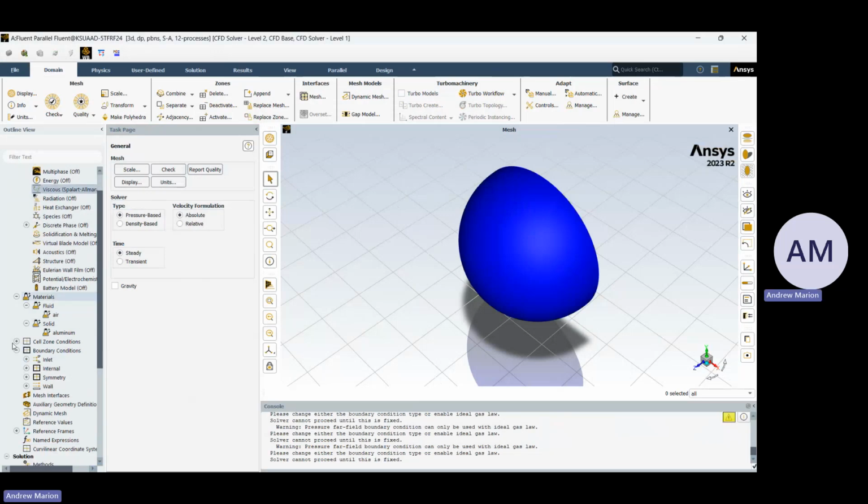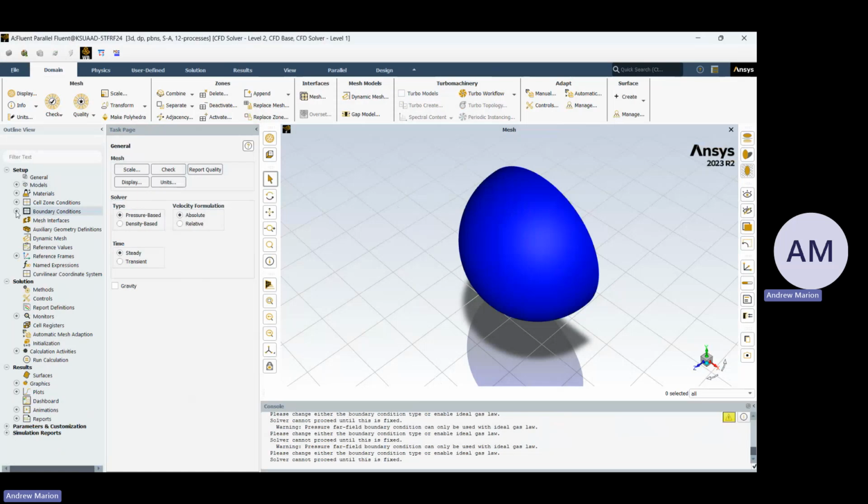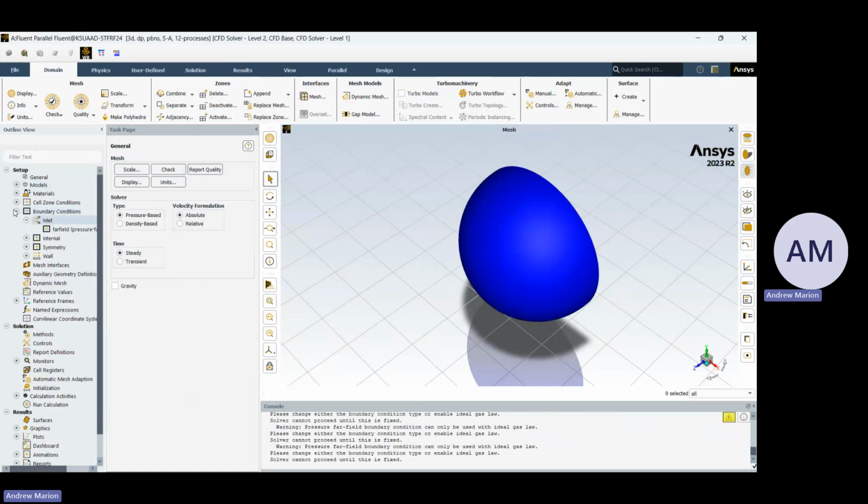Spalart-Allmaras is the most commonly used viscous model for aircraft simulation. I've even gone over NASA papers, and NASA still uses Spalart-Allmaras. Especially in industry, they'll use that because it's simple, because you don't have months to do a simulation. They have deadlines they've got to hit.